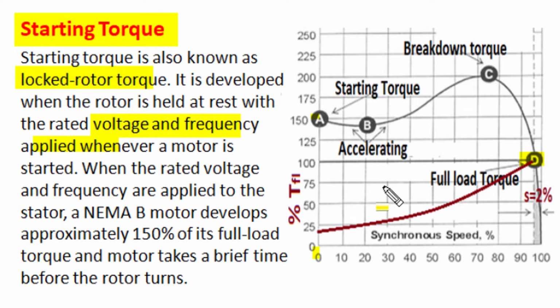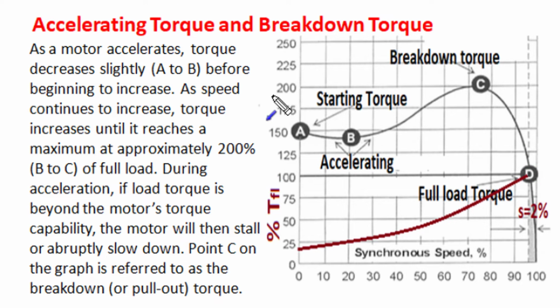But normally the standard designed NEMA A and NEMA B type induction motors are used with fans and pumps, where torque on motor develops only when motor speeds up, or at start position load torque is insignificant, and a small amount of torque produced by such motor can accelerate the motor in routine manner. At the time of start, motor produces a starting torque, and a connected load also demands a certain amount of load torque, and the difference of motoring torque and load torque acts as an accelerating torque, and due to that accelerating torque, motor starts accelerating and attains speed.